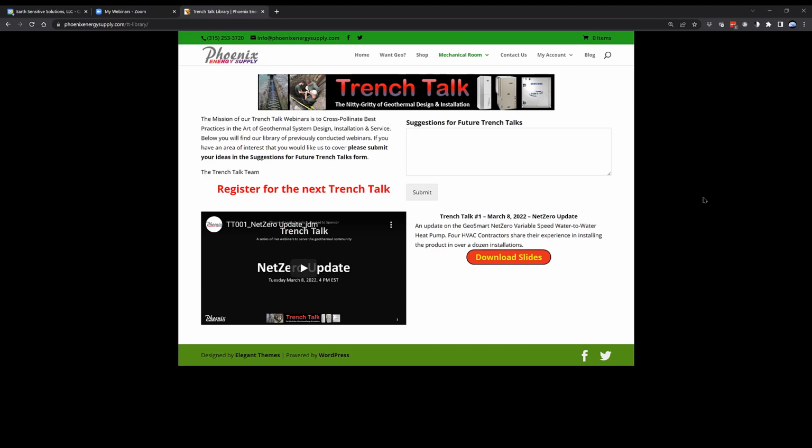And certainly, on a single heat pump application, if the heat pump is variable speed, then yes, I want to use a variable speed pump. But if it's a dual capacity heat pump, single application where you could put a simple 2699 or two of them in, that's probably your most cost effective for a single heat pump application.